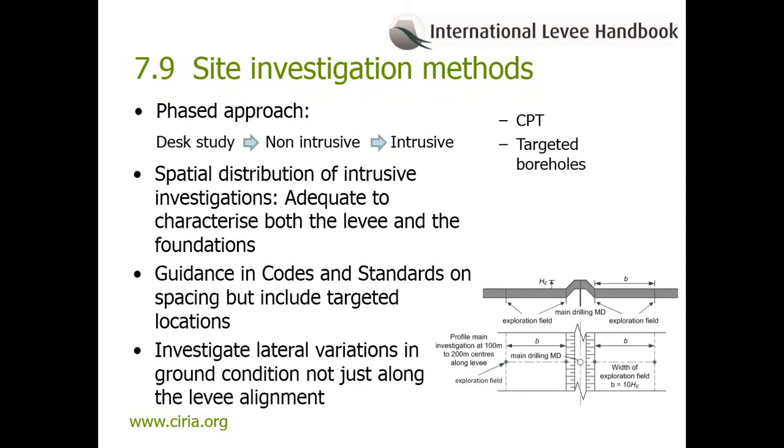Intrusive investigations. This subsection aims to provide an overview on the distribution, depth, and methods of undertaking intrusive investigation. In terms of the latter, the section includes tables summarizing intrusive investigation methods, their applications and limitations. Given the locations where levees are typically sited, the ground conditions can include a combination of soft clays, silts, peats, highly permeable sands and gravels. Not all intrusive techniques are applicable to all soils. This is illustrated in a later slide.